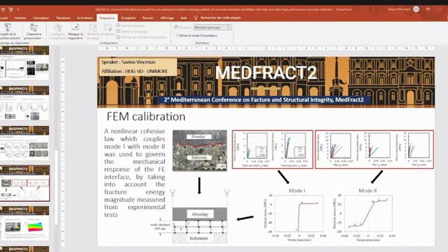in the figures on the left, we can see the evolution of normal stress and shear stress along the interface as the external load increases. And it is important to note that when, in the experimental observation, the crack in the bonding failure starts, in the numerical simulations this corresponds to the plateau observed in the shear stress evolution. If we integrate the shear stress along the interface obtained by the model, we can directly compare the experimental data with numerical data in terms of evolution of lateral shear load versus bond slip.